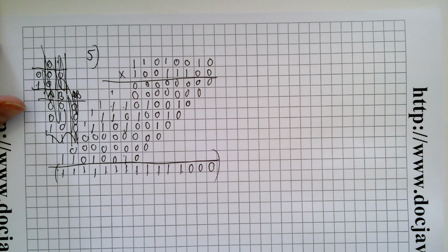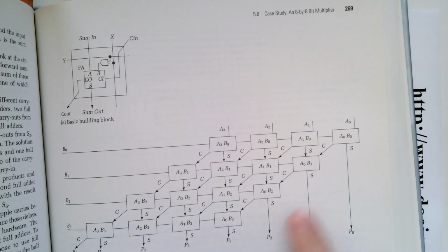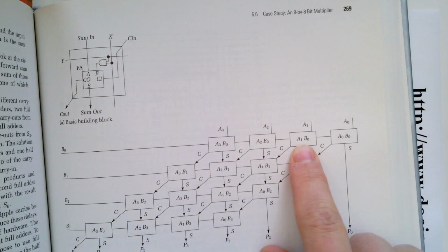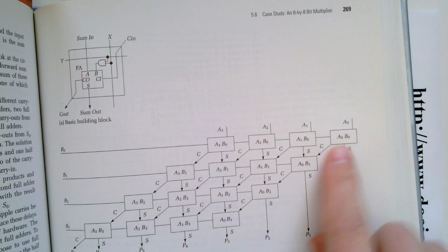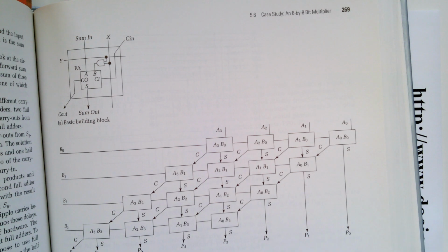And when you start to read about multiplication in the book, you'll see exactly how the hardware is structured in order to make that work. So that's actually quite interesting, because there's hardware that corresponds directly to these multiply circuits. Let me bring one up for you. So here's the network of multiplies, and here's bitwise multiplications being thrown in with carries and sums, and so that's an interesting way to go about doing these things.